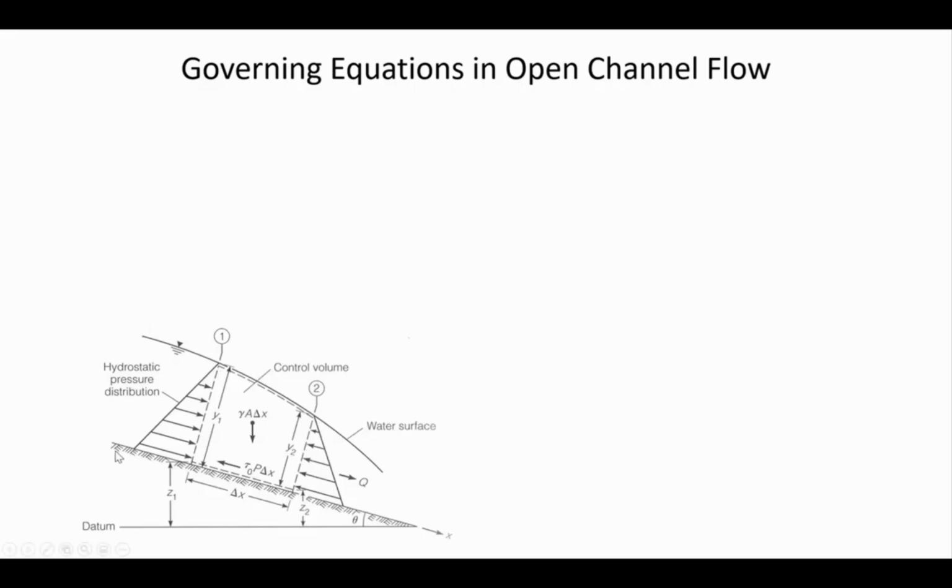Okay, so this side view, this is the bottom of the river, and we're going to do the control volume approach, where you take a certain element of water, and so this is the water surface. See the triangle and those little cross hatches there that is meant to invoke the shimmering ripples of an open surface in contact with the air. So you've got a water surface, and you can see that the depth is decreasing in the direction of flow. The reason why they show that is just to emphasize the point that this equation can apply whether you have uniform flow or non-uniform flow.